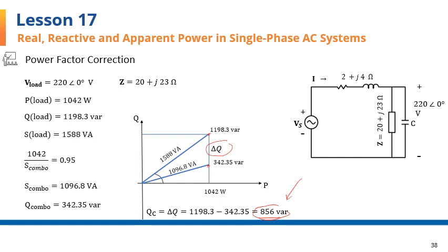Just as I squared Z gives the complex power, V squared times complex conjugate of admittance also gives the complex power. Let me just write this out. The complex power S can be calculated as I squared Z, so if we have the current through an impedance, we can use this. If we have the voltage across an impedance, we can use V squared times Y conjugate to get the complex power. This is what I want to use here for the capacitor.